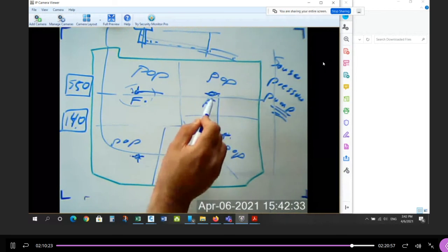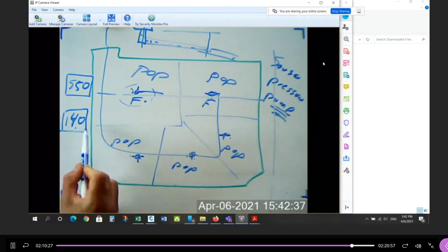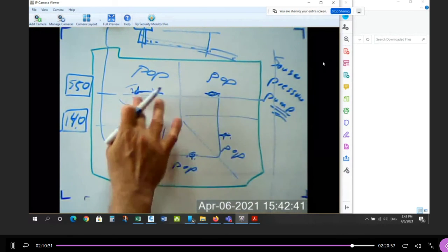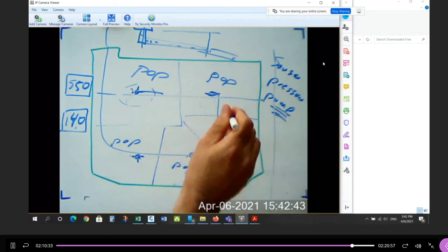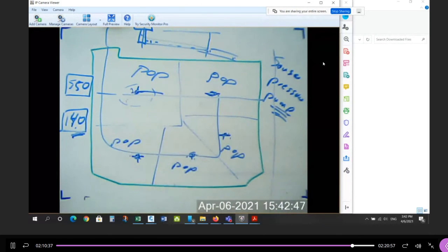Let's say you're drawing a fire flow here. What happens to the pressure at the other locations? Are they all greater than 140? Yes, then it works. And it goes through one at a time, assuming a flow at each hydrant and checking the pressure at all the other locations. If there's 5 hydrants, there's 5 scenarios to analyze. If there's 100 hydrants, it goes through 100 scenarios and so on.